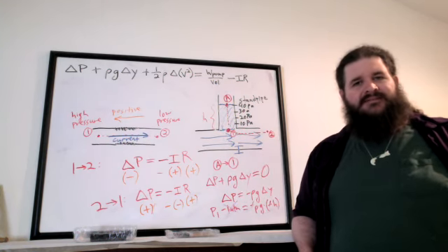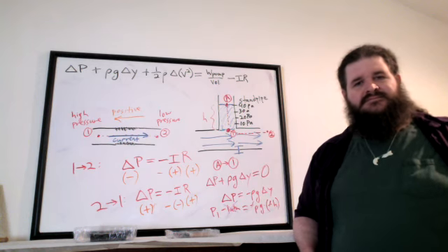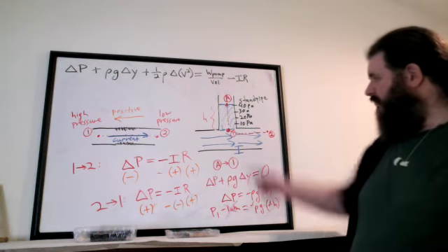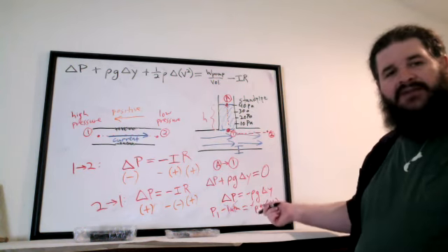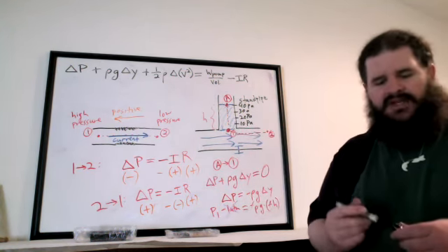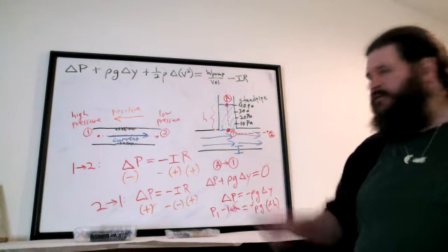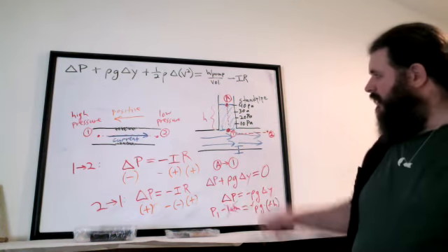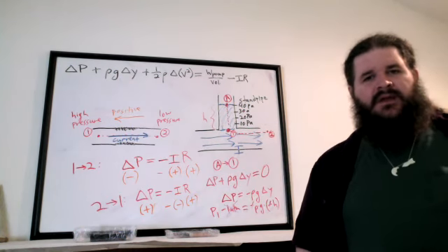Any questions on that? And so you can use that as a general rule. The gauge pressure at the bottom of a standpipe is density times gravity times the height that it rises to in that standpipe. So keep that in mind. We're going to be using standpipes a lot in examples of fluid systems like fluid flowing here. And the standpipe is essentially a pressure gauge.